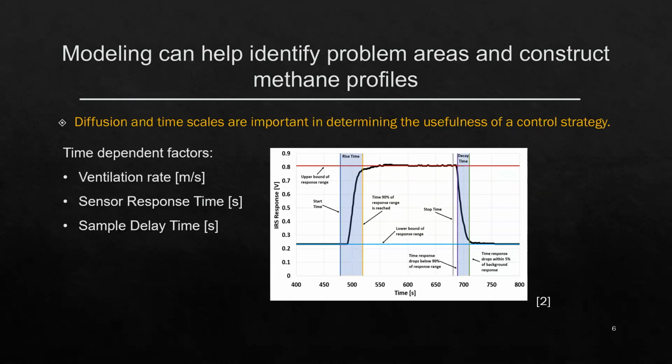So speaking of these timescales and the detectability of our system, here are some system limitations that are inherently present that we must deal with. The sensor's response time being the biggest one. You can see here the sensor requires at least 10 to 30 seconds. This is the rise time of this sensor that we've tested. Our system has two sensors, so this could change depending on what sensor we're talking about.